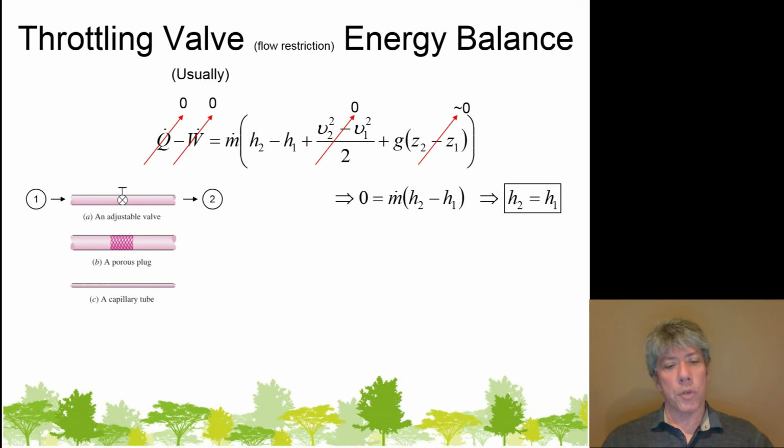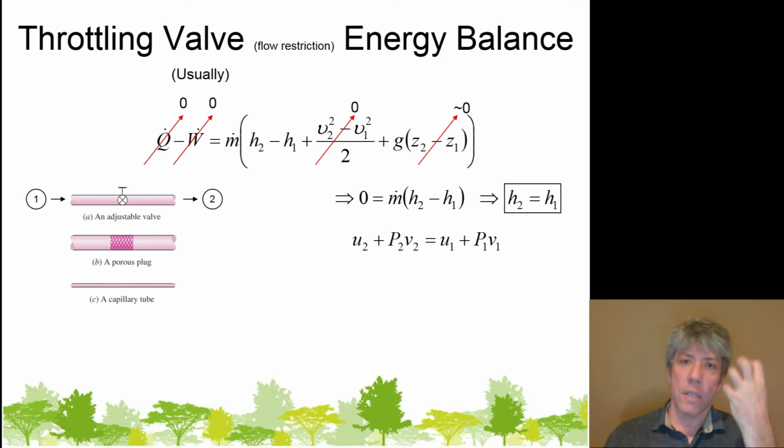Well, remember the pressure dropped also, but the specific volume changes. If you have a liquid and it boils off into a gas, that gas is going to take up a heck of a whole lot more space than the liquid did before it boiled off. In that case, we have to remember that enthalpy really consists of two pieces. It consists of internal energy and flow energy. And the pressure times specific volume, that's the flow energy piece, see?